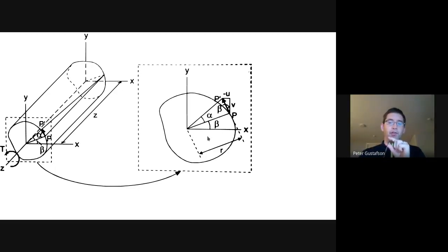In this case, we have a cross-section. It's of arbitrary shape. It's not circular, elliptical, square, or anything convenient like that. It's just a random shape. We'll have a point where we're going to put our XY coordinate system. We're going to call that the center of twist. And in a little while, we'll actually identify where that is. And I've identified a couple of points on here, one called P and the other called P prime. So I've got a point on the cross section that moves as I twist this.